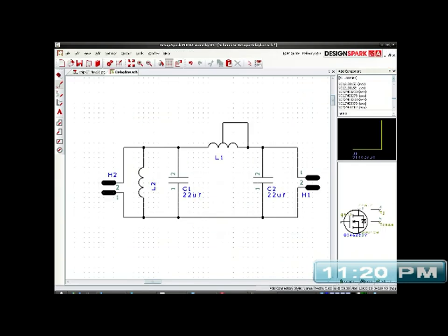Go back to our schematic again. Now, if I put a smaller capacitor in here, the pulse gets a lot smaller. The amplitude is lower. If I put two bigger capacitors in there, no, actually I'm getting it backwards. If I put two bigger capacitors at this point here, the pulse gets smaller and it gets fatter, but it's not strong enough.